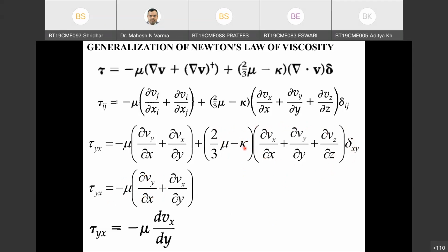When we go for complex problems and transient problems, maybe that is relevant. But as far as basic transport phenomena goes, this is not so important. So you should start with this and put in the appropriate assumptions. This is the generalized Newton's law of viscosity, and both are called viscosity coefficients. This is the dilational viscosity and this is the actual viscosity. Both have the same physical significance. Okay, now what is next?